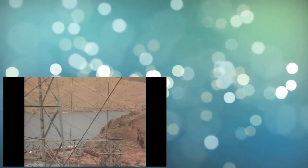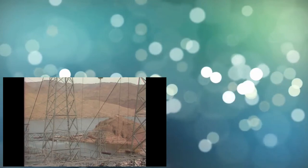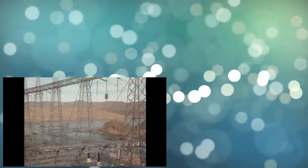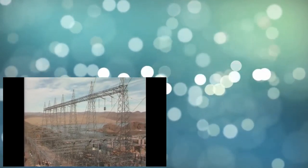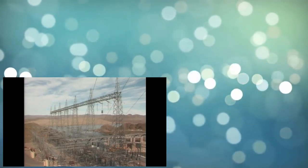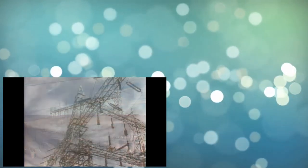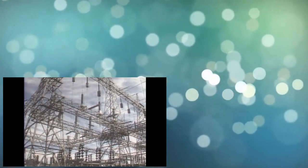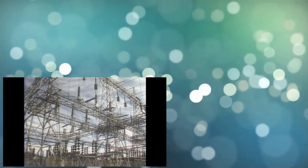In a modern electric power grid, energy is routinely transmitted over thousands of kilometers at hundreds of thousands of volts. But no matter how it's used, the recipient wants all those watts to arrive at a safe and handy voltage. And that's possible only if the electric energy can be transformed up to high voltage, which it takes to make the long trip to the consumer, and back down to low voltage for use at the end of the line. That task, raising and lowering voltage, is hard to accomplish with direct current, but with AC, it's comparatively easy.